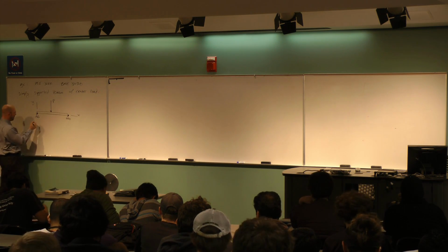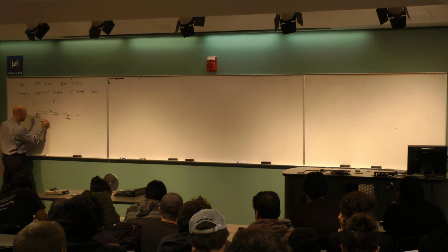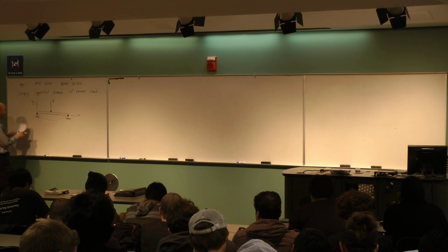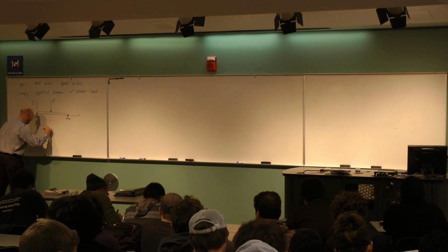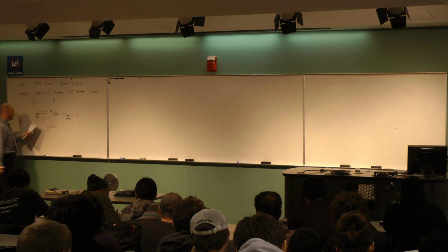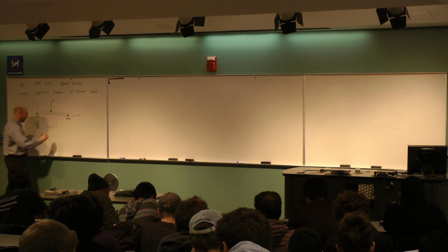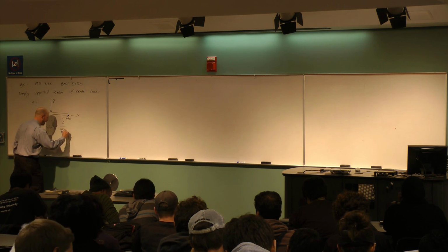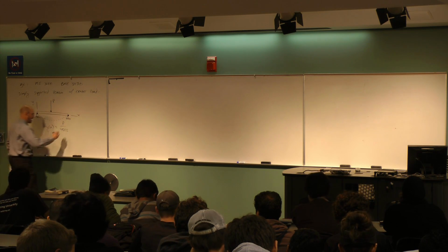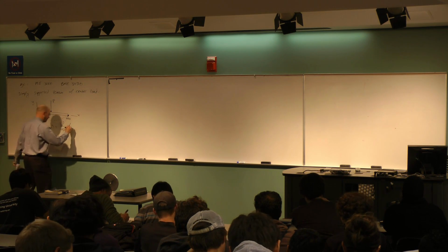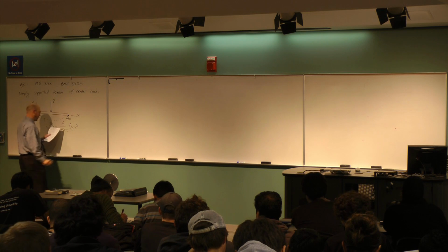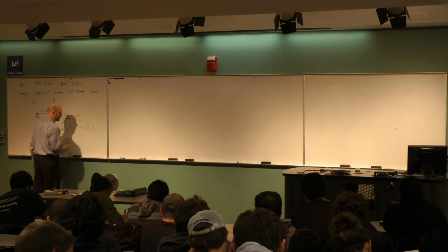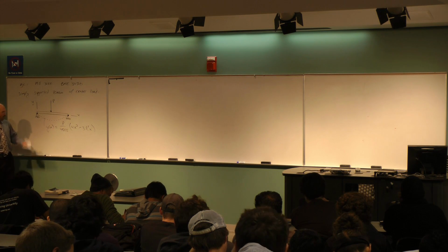Okay, and so you can sketch the basic shape of this initially. It's going to do something like that, right? And so this is my y of x. Y is a function of x, the actual deformation. And it turns out the answer for this guy is as follows. It's P divided by 48 EI, and then this guy's a cubic polynomial. It's 4x cubed minus 3 L squared times x, okay, like that.